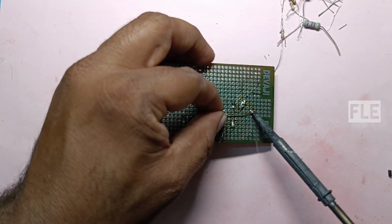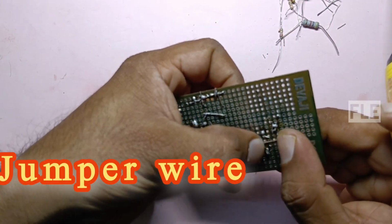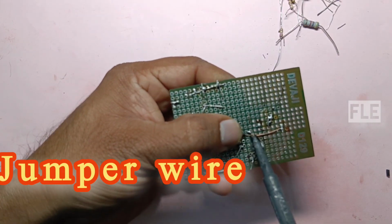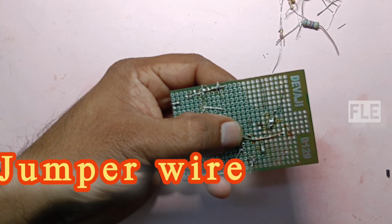Take a jumper wire. This wire is connected from the positive terminal of the 2.2 microfarad to the center terminal of the 6.8K resistor and 5.6K resistor.